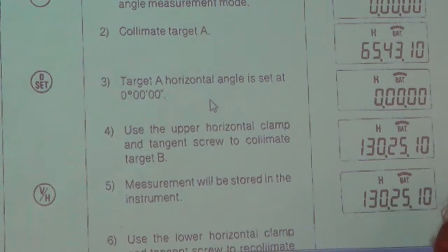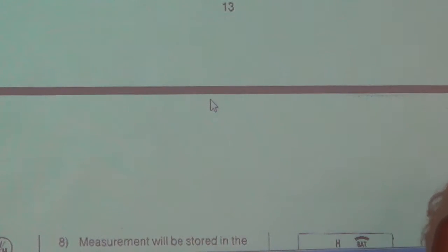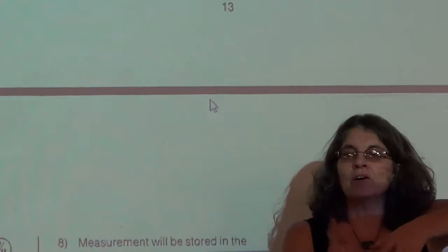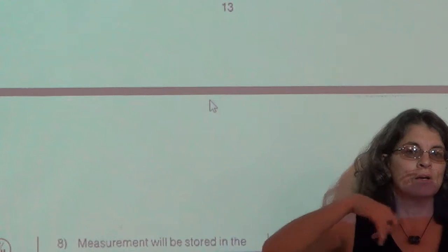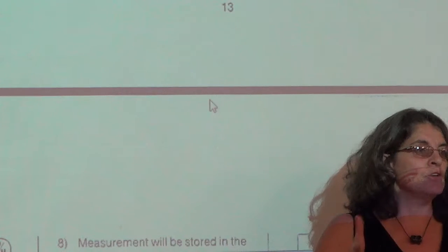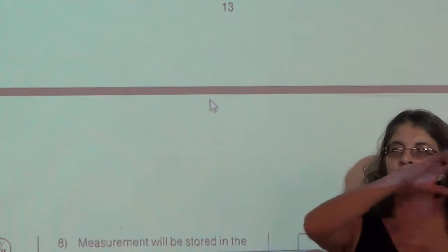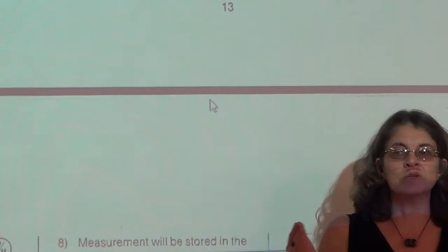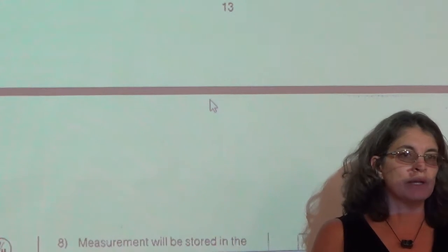And you didn't have to lock, unlock all those open plates and stuff, you know? But you will have to lock it somewhat, because if you're turning your equipment and the angle is not changing, what is locked and unlocked? So you have it on A, you have it on 0, right? The angle says 0, and you keep spinning it, and it's still on 0, and it doesn't change. What is locked? What's unlocked? The bottom plate. So then you gotta lock the bottom plate.